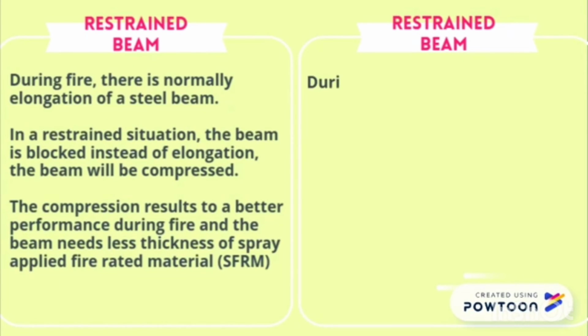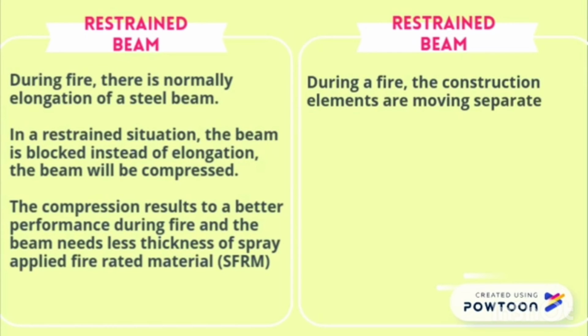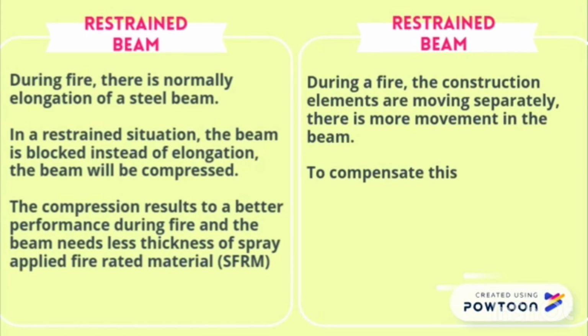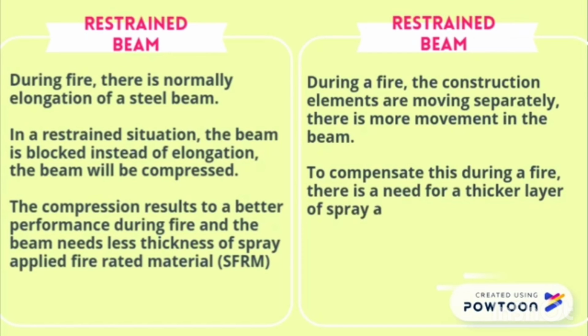During a fire, the construction elements of an unrestrained beam are moving separately, so there is more movement in the beam. To compensate for this during a fire, there is a need for a thicker layer of SFRM material.